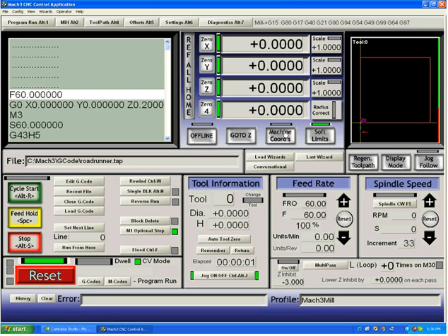Now we have our secondary system. Let's say we jog away from zeros. We've got a piece of material on our table, so we're going to jog up to it. We're going to move our Z down. Now we're touching our material, which is out here somewhere, and we now zero our axes.